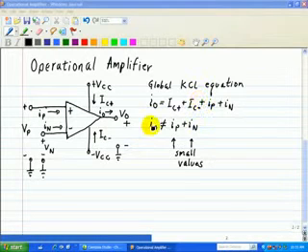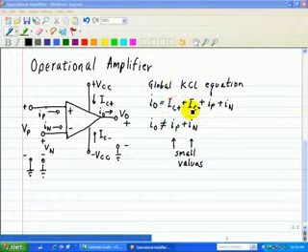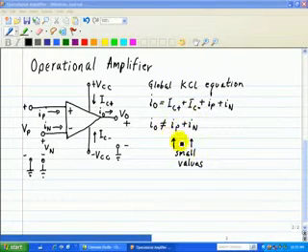And then we also note that the outgoing current does not equal the 2 ingoing currents at our input terminals, IP and IN, because they don't include IC plus and IC minus, and these values, IP and IN, are usually small, as we'll see. In fact, we'll use this to define our ideal characteristics associated with an op-amp.